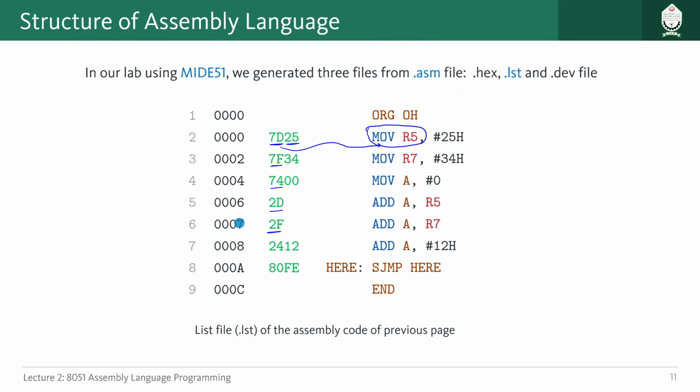At the same time, our program counter, PC, also has to increment properly, so that we can properly fetch each instruction. Whenever we start, our program counter will start from 0000. That will be the data initially saved in the program counter.